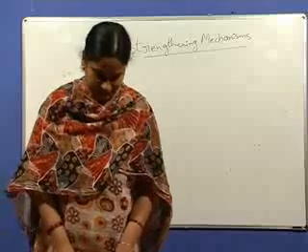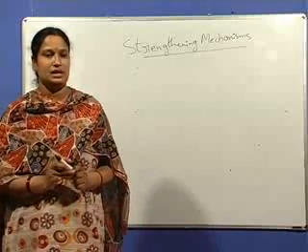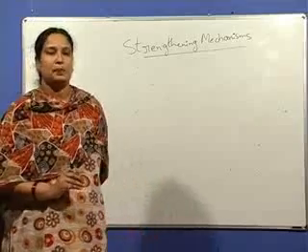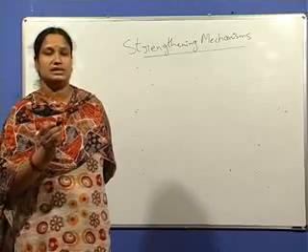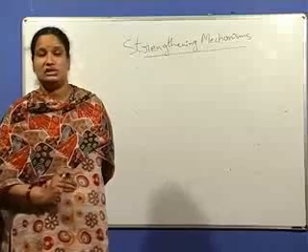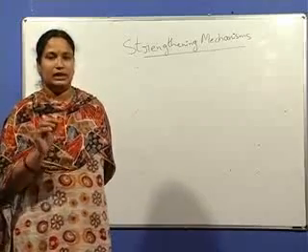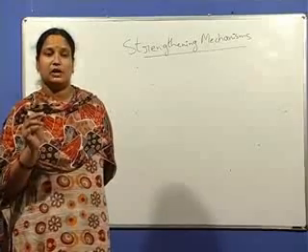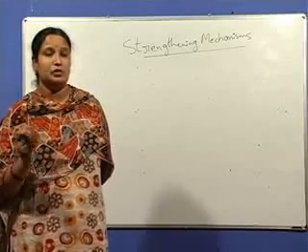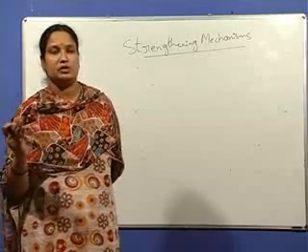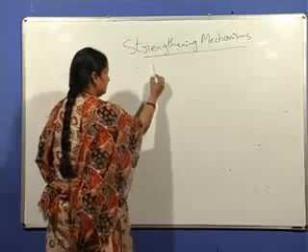So the main requirement for an alloy to be precipitation hardenable is that it requires a sloping solvus. Sloping solvus means solubility should increase with increase in temperature and solubility should decrease with decrease in temperature. This is the main requirement for an alloy to be precipitation hardenable. And moreover, the precipitates that are formed in precipitation hardening must be coherent with the matrix. Then only it creates more strains, thereby more hindrance to the dislocation motion, thereby a stronger alloy. So sloping solvus is the main requirement.